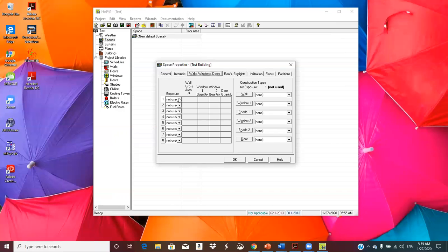Okay. Let's put in exterior walls. And so I'm going to have some, whatever direction the wall faces. So I'll say I've got north. And let's see, I've got 5,000 square feet, so that's about 70. So I'm going to say this building is 100 by 50. And I'll say the walls are 15 foot high on the exposed side. So yeah, 100, this would be 1,500 square feet. I've got windows. Let's say I've got 8 windows in that wall. And I've got 1 door.